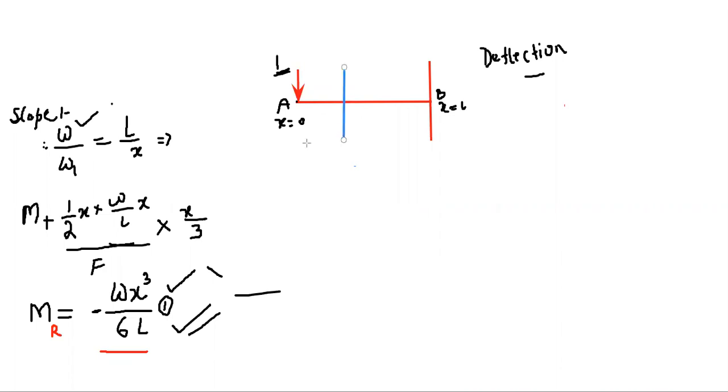Cut the beam out. The section that comes out will be like this. Here we have a force of 1 unit acting at this point. This total distance is x. Here we suppose the shear force is V and the bending moment is M. We have to find this bending moment for this case.